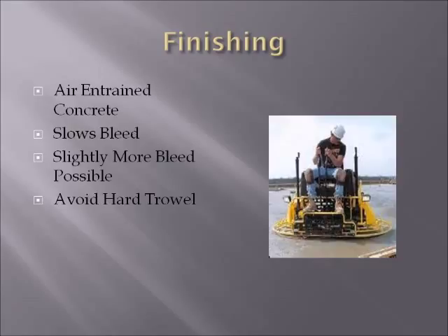Lightweight concrete does not blister or delaminate any more than any other air entrained concrete will, as long as the procedures are followed properly. Make sure that your finishers know that it is air entrained, and make sure that they have experience working with air entrained concrete prior to the project or any concrete placement.